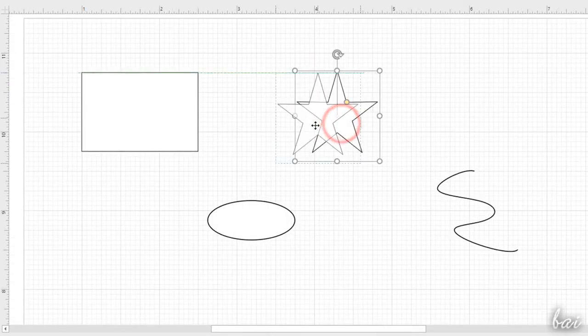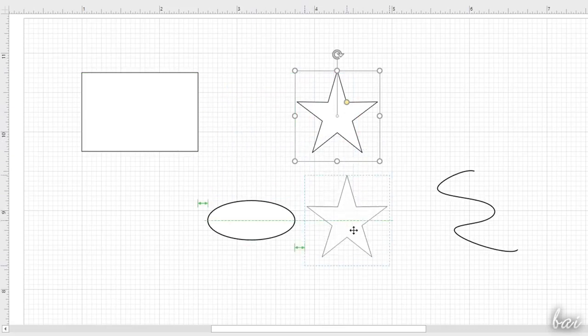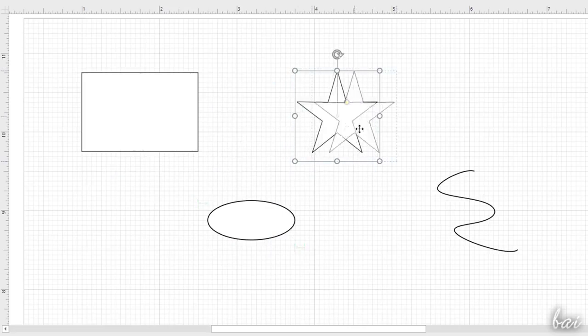To move the object, click and drag it directly. Visio will help you with several green guidelines in order to place and align your object correctly. Remember that you can avoid any snapping or guideline by holding down the Alt key, whereas hold down the Shift key to move horizontally or vertically.